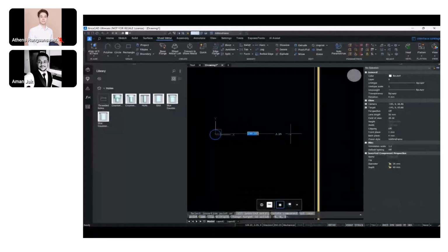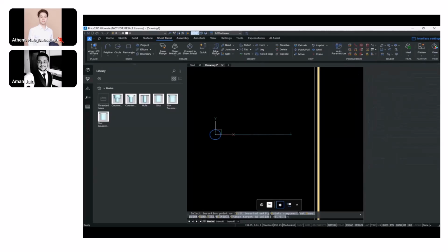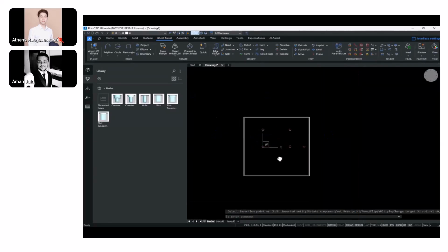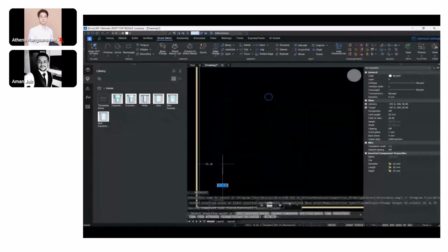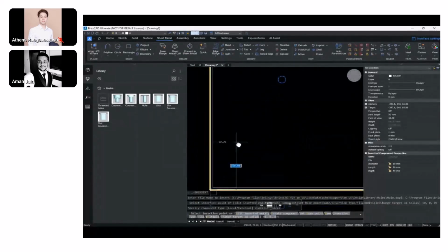So here I'm placing one more hole, which is for the lock, where the lock would be placed. Let's say this would be at a distance of around 140. Now, this is smart placement of the holes as well. Ideally, I'm able to place this in conjunction with the holes that I had already created, and I can add distances based on their positions. So this becomes easier for me rather than creating sketch geometries for each and every feature that we add, right?